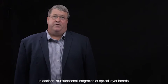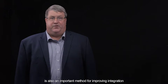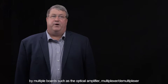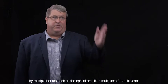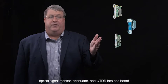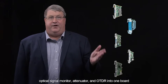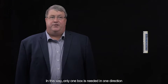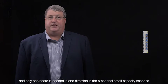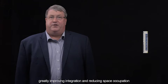In addition, multifunctional integration of optical layer boards is also an important method for improving integration. For example, Huawei has integrated the functions that need to be implemented by multiple boards, such as the optical amplifier, multiplexer-demultiplexer, optical signal monitor, VOA, and OTDR into one board. In this way, only one box is needed in each direction, and only one board is needed in one direction in the 8-channel small capacity scenario, greatly improving integration and reducing space occupation.